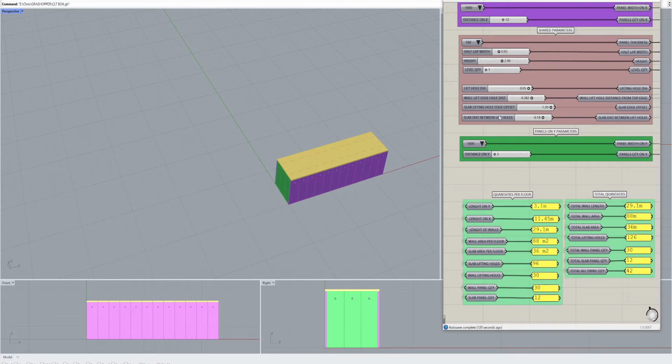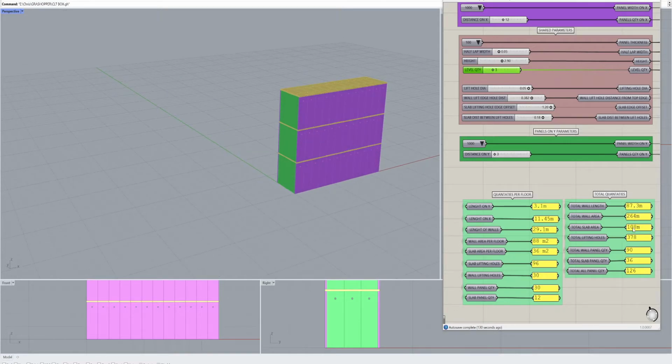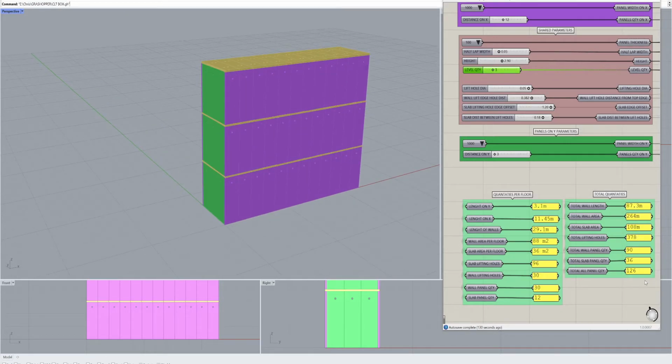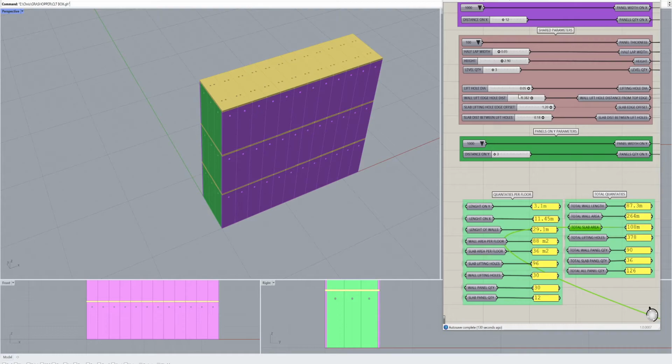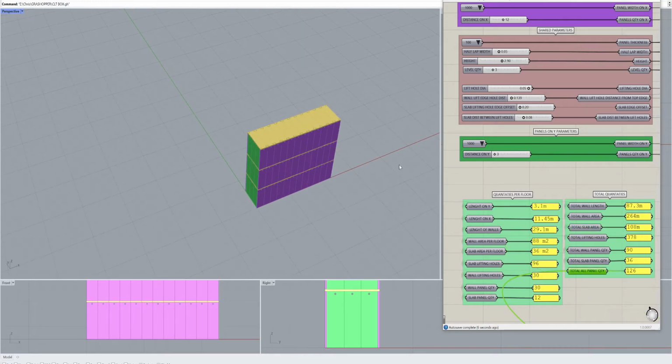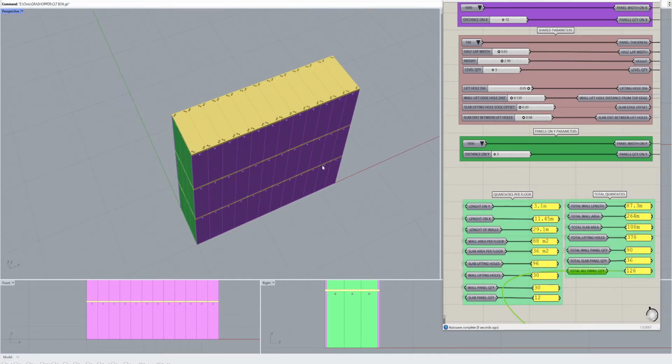And then when we start to increase the quantity of the levels, you can start to see these building up over here, and it's giving you these overall figures. It gives you the figures of the lifting holes, of the slab area. So 800, this is 108 square meters. Just playing around with this. Total panel counts, we've got 126 counts here, so 126 lifts essentially.